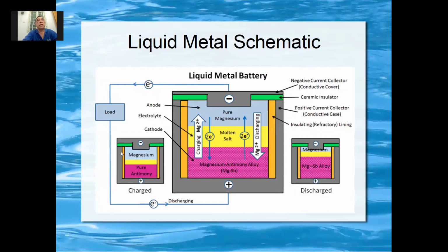So at room temperature, they are solid, no chemical reaction. Then you can ship it out in a container, no problem, because it's not a chemical, it's just a piece of solid metal. So there's no chemical reaction, nothing. So there's no safety issue. So you can ship the whole container of battery at room temperature, just ship it out, no issue. So when you want to operate it, then you must have a mechanism to heat it up to 500 degrees, and then it becomes molten or liquid, and then it starts working.